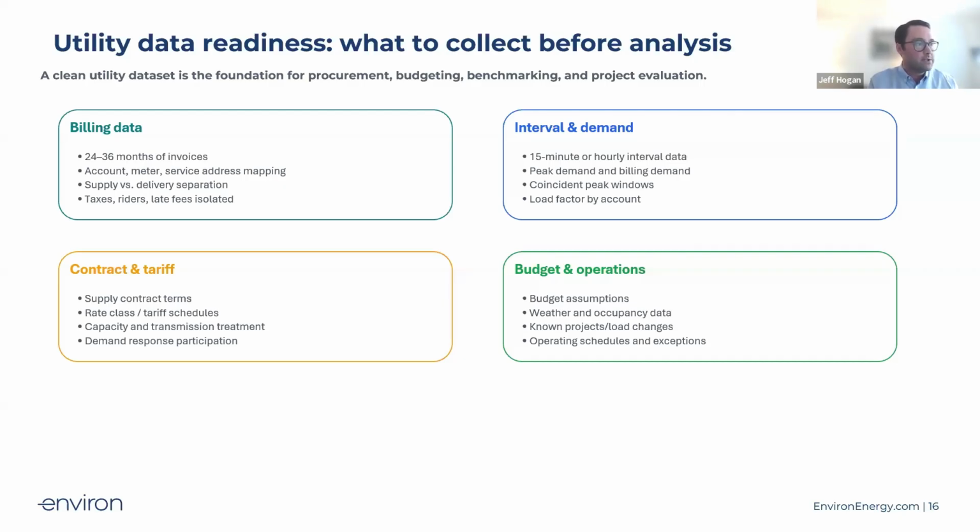Interval data is very helpful when looking at how your facility performs. Interval data is typically a real-time available asset or resource to most through your utilities or through other systems. Billing data is kind of a lagging indicator. You don't really know how you performed until you get your report card. But the interval data, if available to you, can give you some real-time performance, especially if you're looking at peak load shaving in real time. It can be very helpful to understand if I turn this chiller on, if I turn these pumps on, what happens in the morning or during the afternoon, I should say.